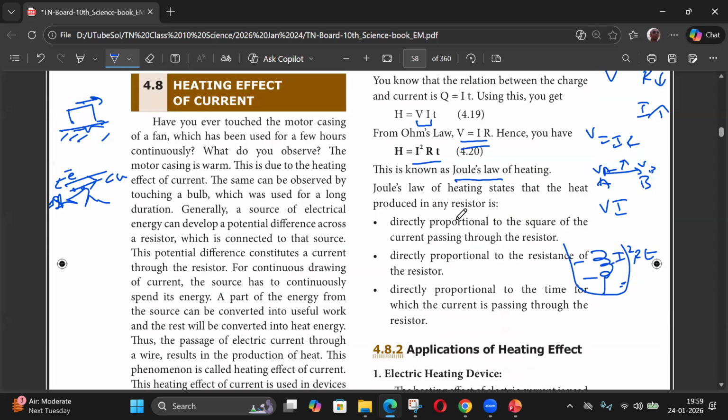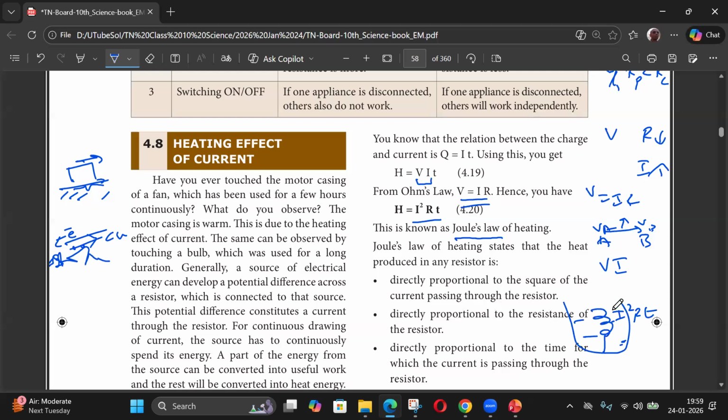And it will be hitting those water particles, sir? No, not heating. Here this thing will become hot. Temperature will go up. Say the coil temperature is T2 and the water temperature is T1. So there will be a heat transfer from this coil to the water. Heating is happening inside this wire. That's not going to hit this water. After that is heat transfer. There's no electricity transfer. Once this coil gets heated up, then there is heat transfer between this coil and the liquid water.